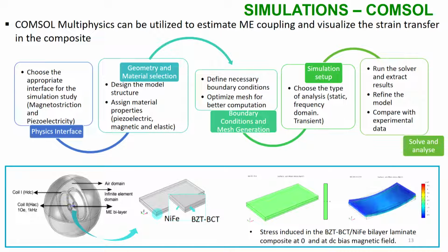The boundary condition, the clamping, becomes important, so the edges are either free to move or have whatever conditions you are imposing. Once you get the boundary conditions, you generate the proper mesh and then do the simulation. Once you do the simulations, you run the setups and then compare with the experimental data. That is very important. You have to compare the experimental data and try to match it. So, take a known case, do the whole thing and verify, then go for variations.